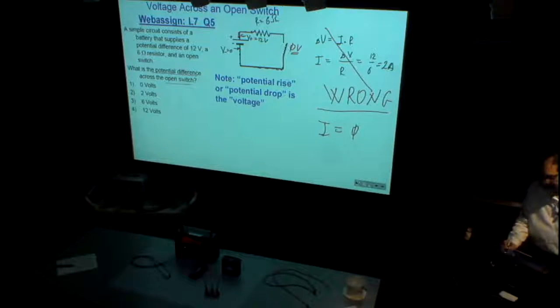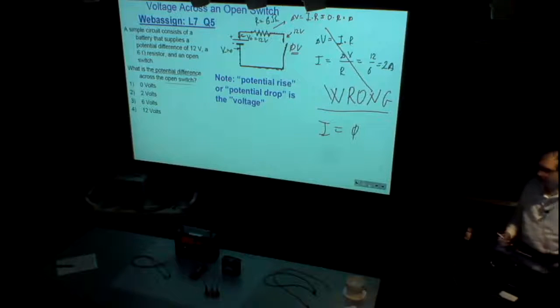Now, what is happening inside this resistor? Does it change potential or not? That's the most important question. If there is no electric current, there is no potential change. Potential change through the resistor equals current times resistance. And because there is no electric current, there is no potential change. That was one of the rules. So electric potential does not change through this resistor. And then another ideal wire, so electric potential remains 12 all the way up to the second end of an opened